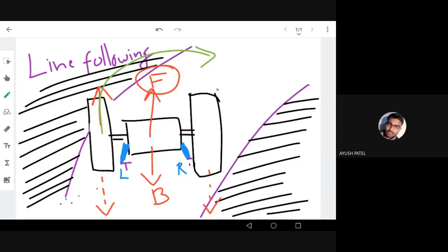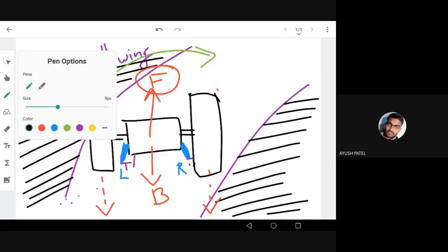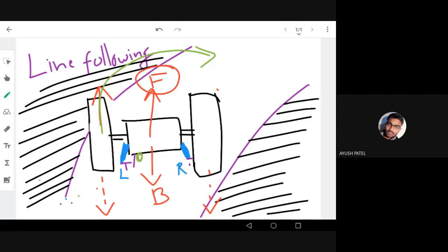So we have a transmitter. Now we need a receiver also. The receiver is also placed here, nearby the transmitter, right? Now the transmitter will be transmitting radiation towards the road, to be received by the receiver. When it is a white reflective surface, the receiver will definitely receive the transmitted IR pulses, right? When it is a dark surface, the receiver will not receive the transmitted pulses, right?